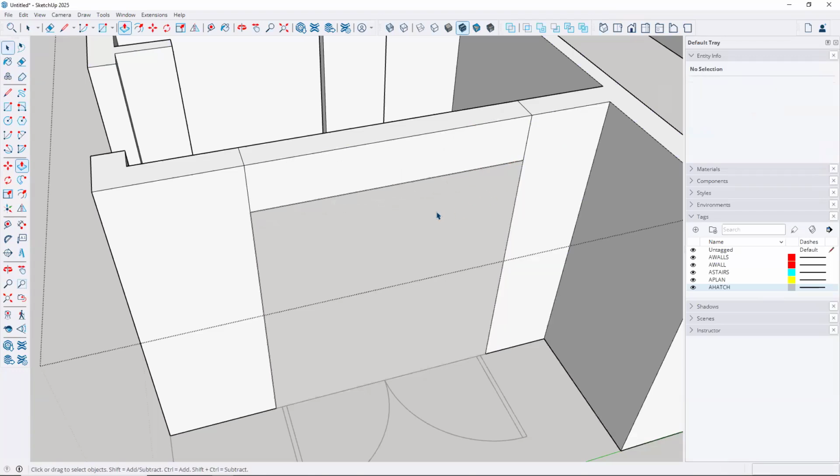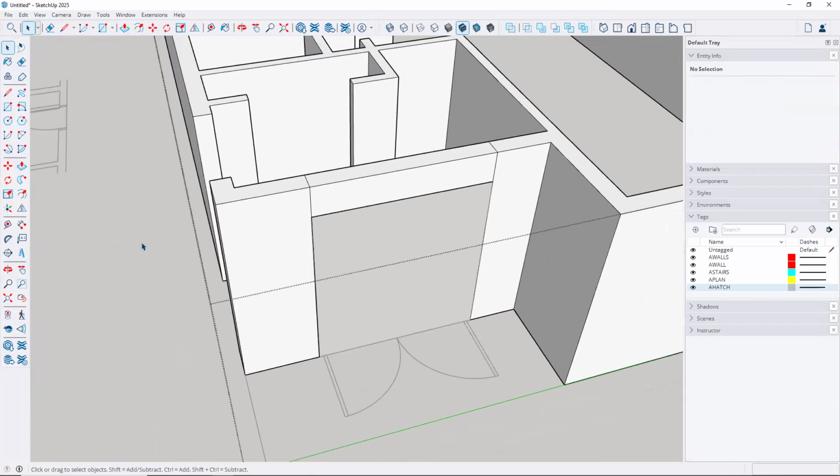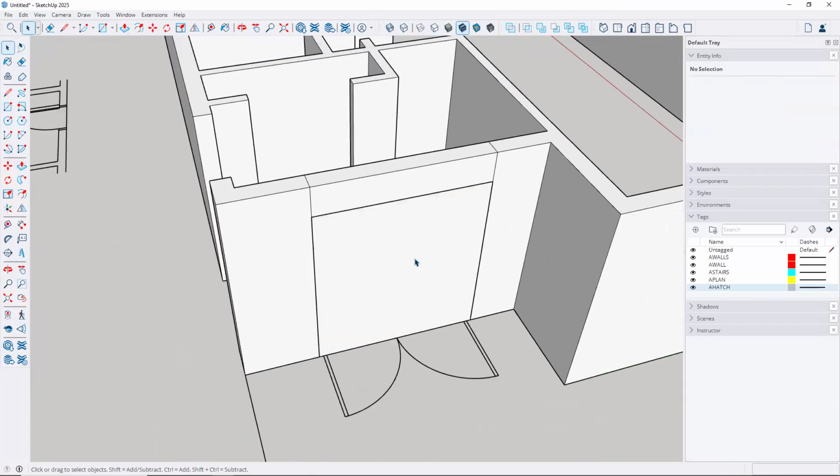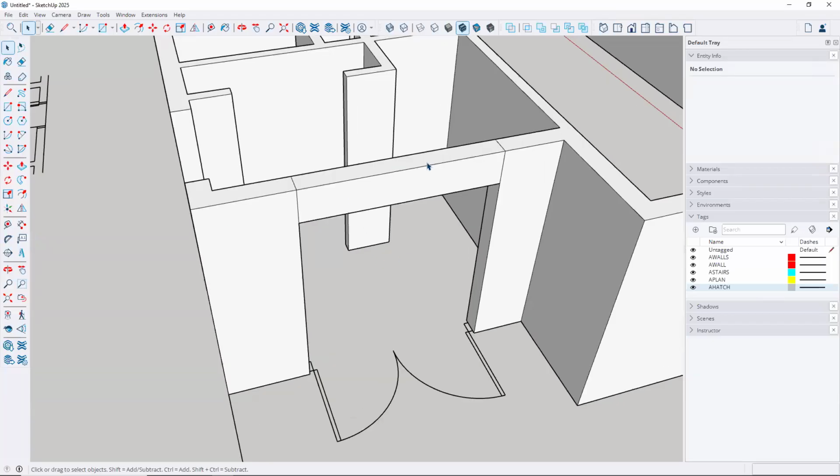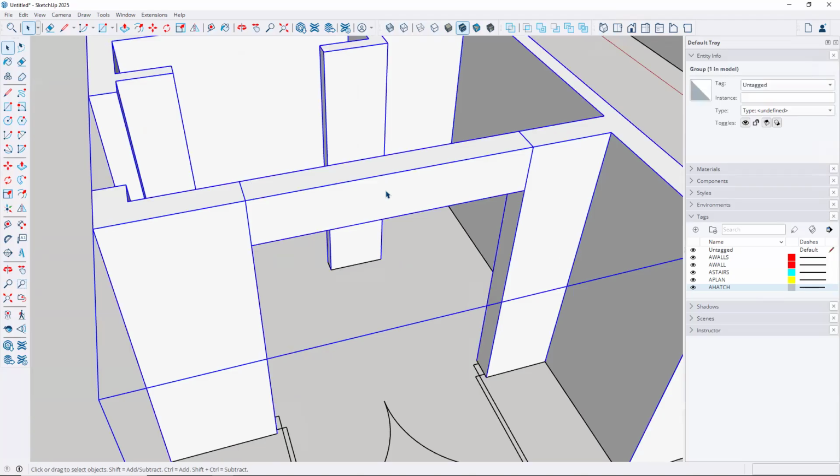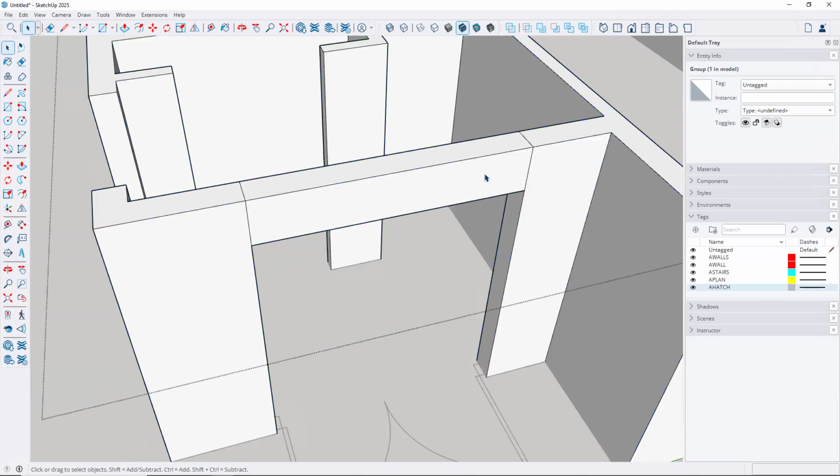And then tap the space bar. And then just for a moment, I'm going to click outside. And then triple click this solid. And then just delete it because it served its purpose just to give me that height. And now when I look at this solid, I'm in good shape. If I double click it, first of all, notice how it says the type. It doesn't give me a value. So there's extra lines here that I need to get rid of so that it does show me a volume. So I'm going to double click.